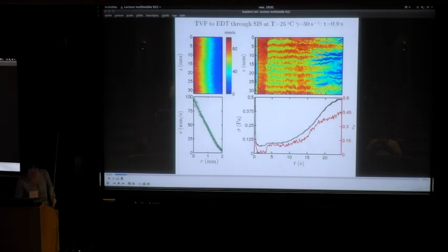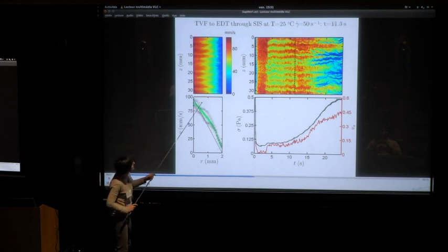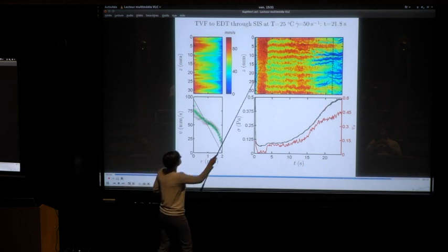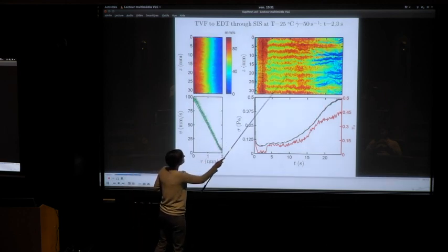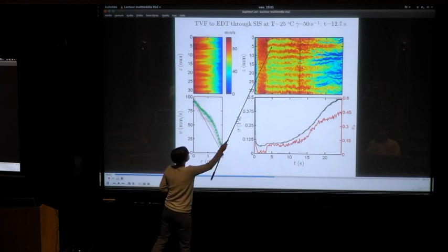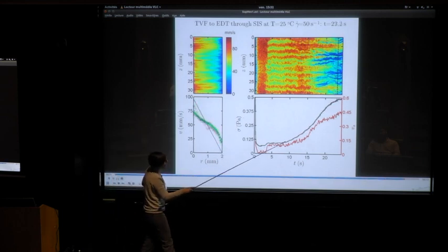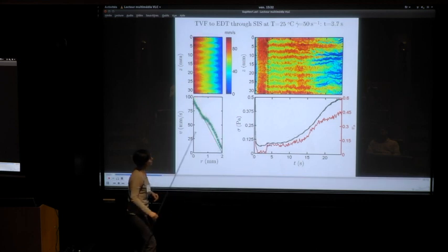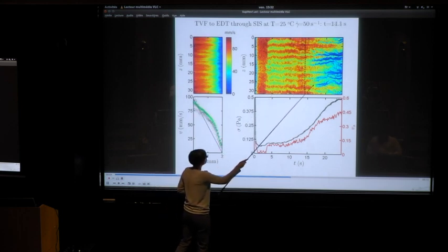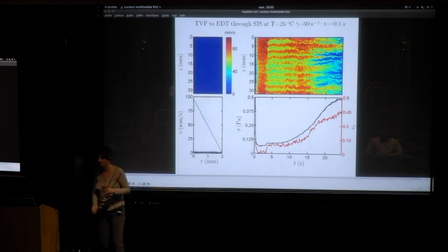The other case is a bit more complex. In that case, at the very beginning, the flow is homogeneous, and then we have this first instability. If you compute the Taylor number here, it is larger than 41, and so this structure here is purely inertial. But after the induction time, when the shear-induced structure builds up, this Taylor vortex flow is completely modified due to the elastic forces, and we end up again with a strongly disordered flow state.